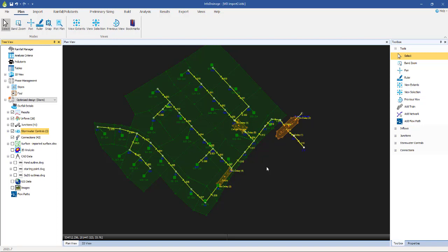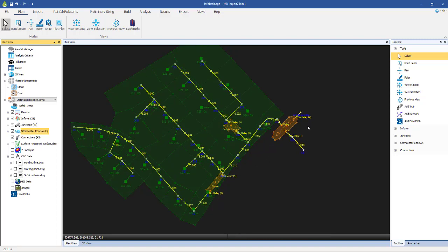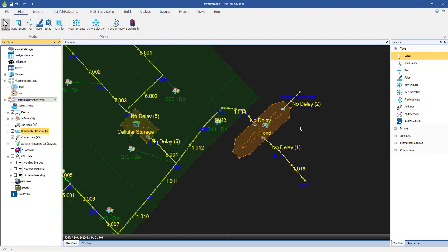When it comes to the third element, subcatchments, I'll show you the functionality that we have there. We've got a great deal of functionality, but there are still things that you need to do within InfoDrainage whilst you're doing that round trip process. When it comes to the 4th and 5th elements, the storage structures and the associated ancillary structures, such as the orifices and the weirs, then there is certainly more work to do here.